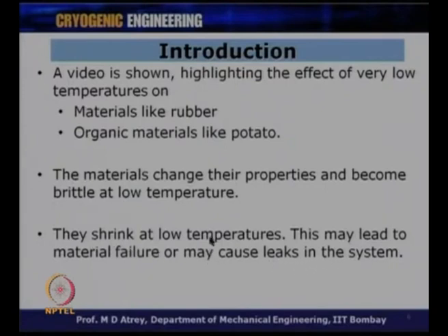So, material shrinking at low temperature: some materials shrink more, some shrink less. If I know that the material shrinks at low temperature, and how much it shrinks at various temperatures, I will have to take care of that shrinkage right in the design aspect. I should have this flexibility allowed, some elasticity component kept, so that shrinkage or expansion of the material when it gets warmed up to room temperature is allowed, and this aspect has already been taken into account in design.